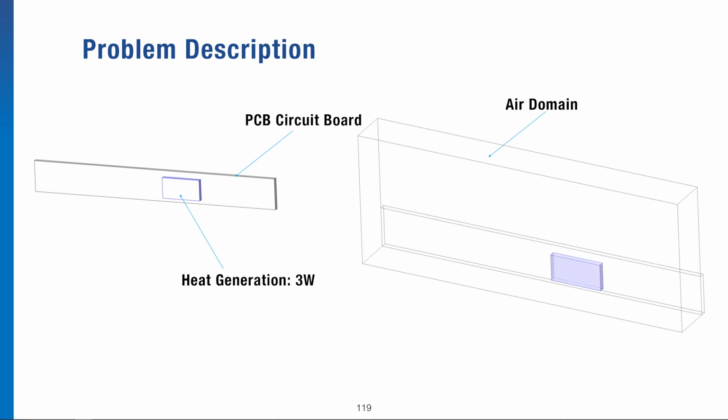So, within this framework, we have a PCB board which itself does not generate heat. This is generally consistent with real industrial scenarios. And on this PCB, there is a power management chip, also known as a power management IC. It has a certain amount of heat generation. For this, we set the heat generation to 3 watts. For such a chip, 3 watts is actually considered a normal level. This is because power management chips generally have a high efficiency. Therefore, 3 watts can correspond to a much higher final application power.